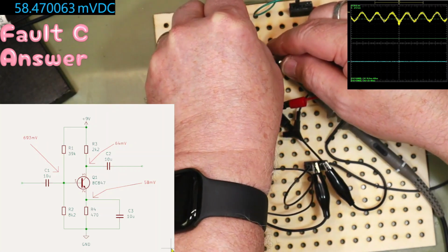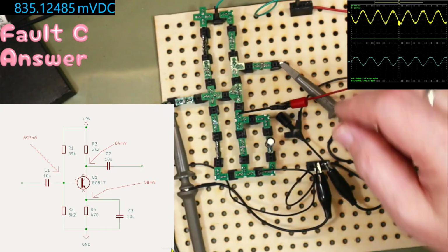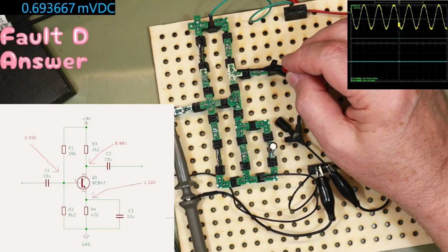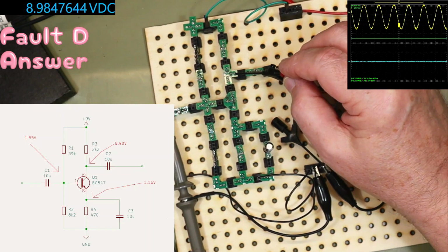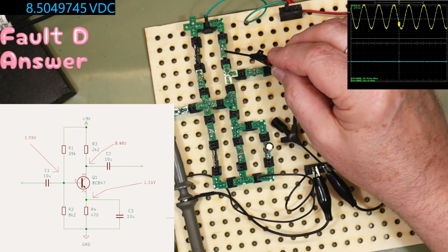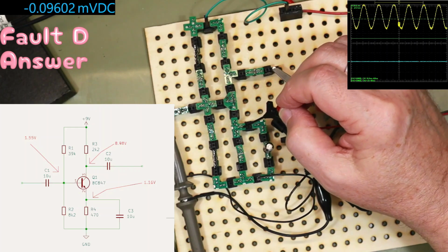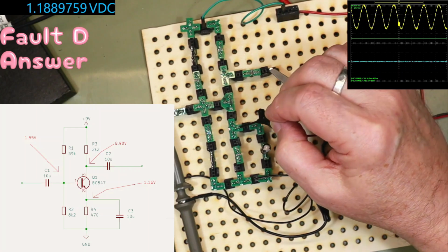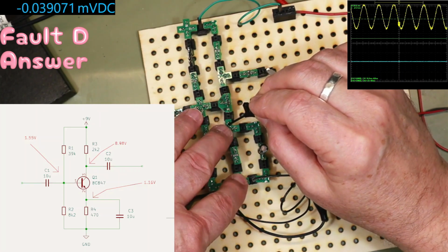And if I put it back to where it should be, everything will come back to normal. And why is this voltage close to the supply rail? Now if it's close to the supply rail, then there can't be any current flowing through here. No current flowing through here means there is no current flowing through here. So this point must be open circuit, which is probably why when you connect to it you get different values. The meter's not behaving if I put my finger across it.